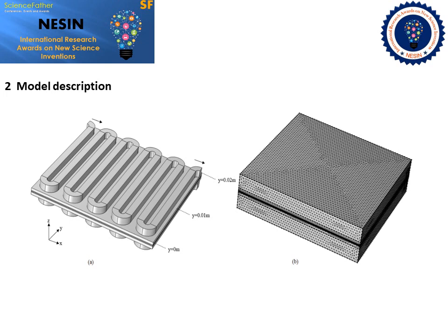The protons generated at the anode are transferred to the cathode through the PEM, and the electrons generated at the anode are transferred to the cathode through the pipeline and the external circuit. Figure 1b shows the grid division of the computational domain of the PEMFC model with additional pipeline.